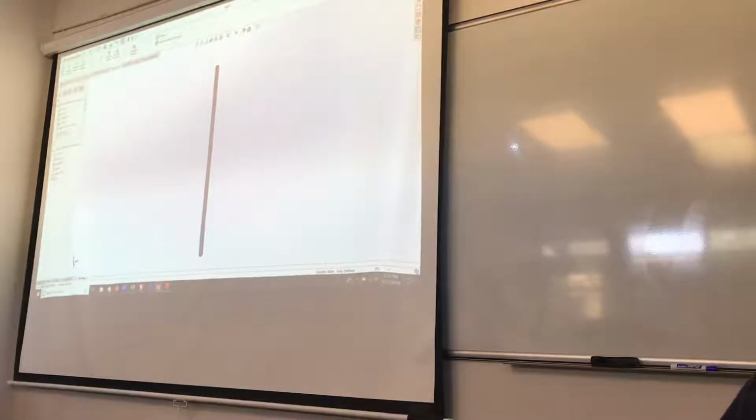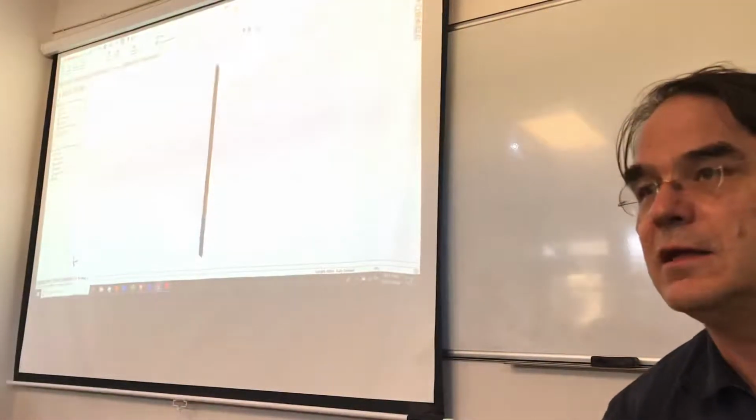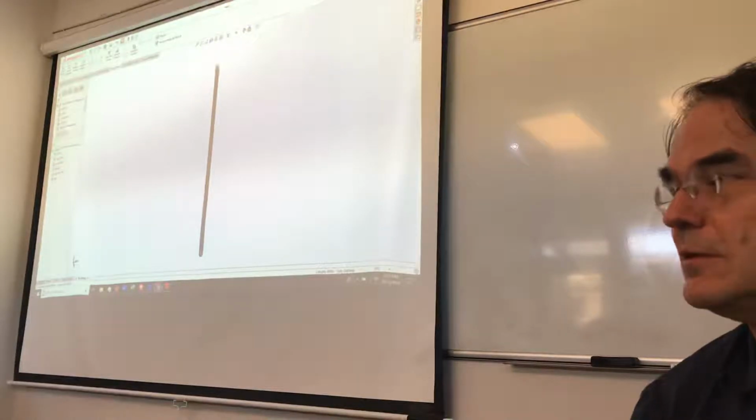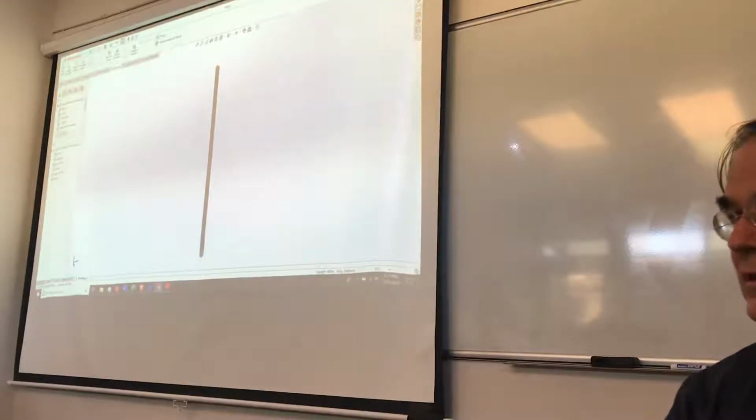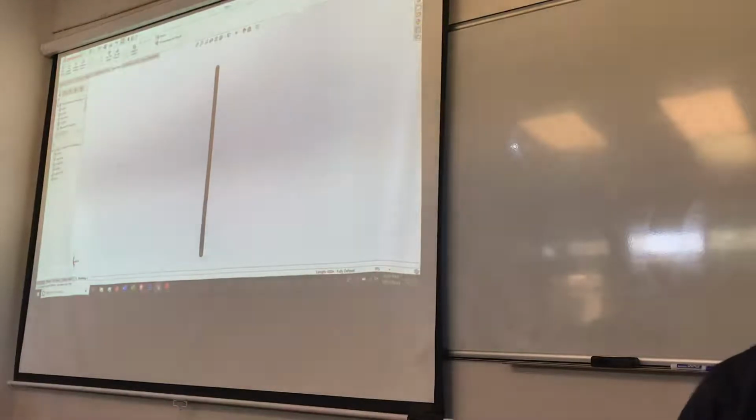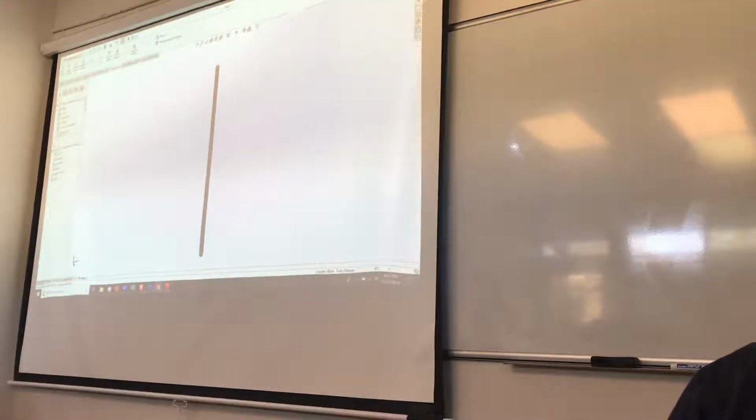It's pretty happy here. We're gonna pick a material on this, right? We're gonna apply a material. And of course, it doesn't really matter what material it is because it's going to be a steel. All we really care about is what the E is. Any of the steels will give us the exact same results because the modulus is essentially the same for any of them.